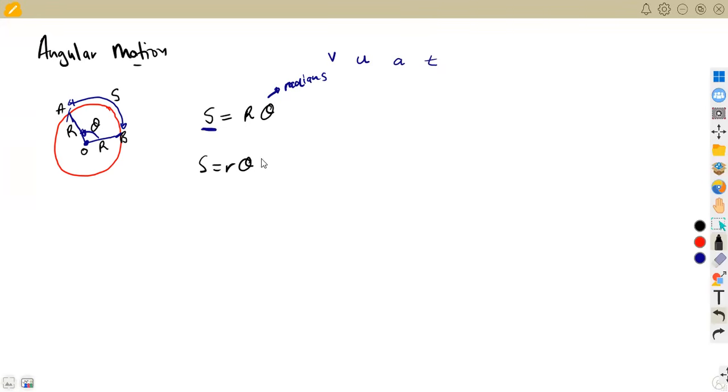It's one and the same thing, meaning to say you can find this theta, which is the angle that we are given in this case, which is now our angular displacement. This one is just a normal displacement, but this theta is now our angular displacement. So we have angular displacement, and this being our linear, we've got linear displacement, just like linear velocity. This will be our linear displacement, and this being the radius of the circle. But this theta, which is our angular displacement, is the angle that we are talking about, but measured in radians. That is what I'm simply saying.